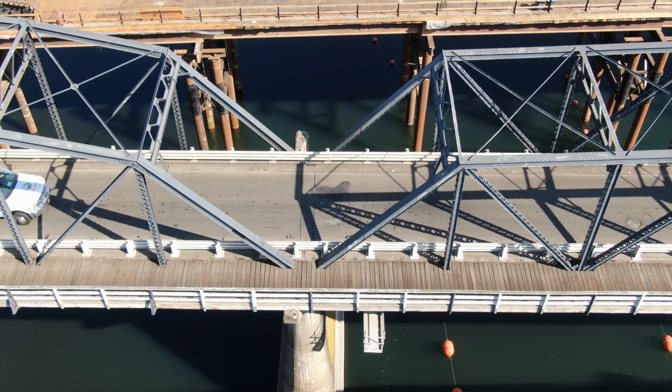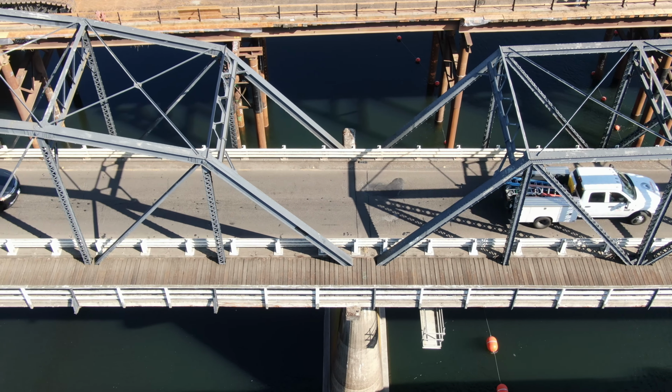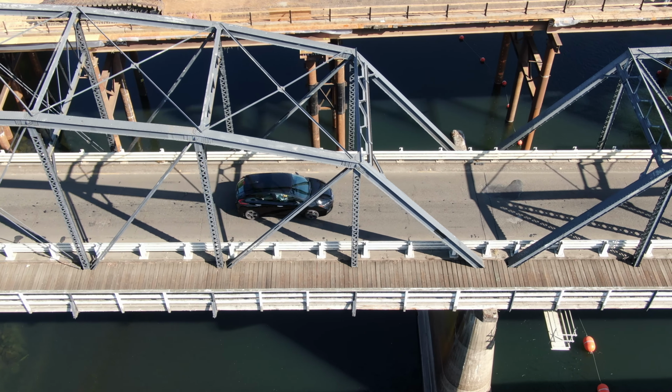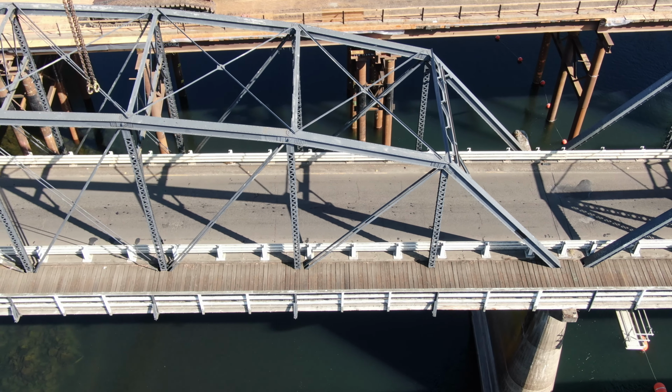Seismic loading, that's going to come though from the bottom of the bridge. It's going to be transferred from the foundation up through the columns to the bearings into the superstructure. And it's going to be more complex. It could be a combination of vertical loads, horizontal loads. It could be a series of aftershocks. The bridge is going to be vibrating.